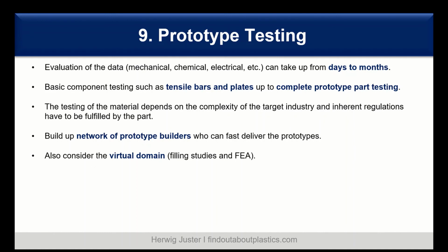And so here it is important to build up also a network of prototype builders who can supply you with fast prototypes, either injection molded or 3D printed. Also important is to consider the virtual domain using filling studies, and also finite element analysis for checking the mechanical stresses in the part.